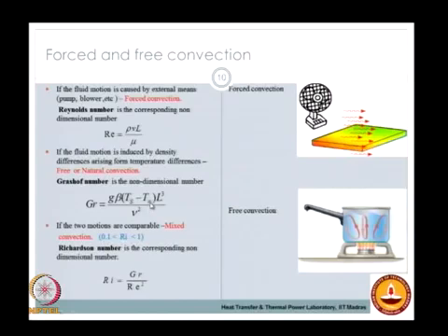In the case of Reynolds number we use the ratio of the inertial force to the viscous force. Here the inertia is replaced by the strength of the buoyancy force, which is related to the temperature difference between the hot side and the cold side.